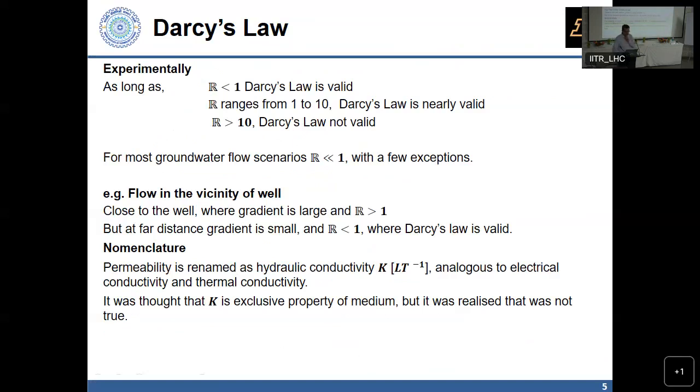We often see the term permeability. Permeability is sometimes different from conductivity depending on which sub-area you are from. In soils, people think of permeability as perhaps what we would call intrinsic permeability. It also comes from similar constitutive relationships like Darcy's law, where the flux is proportional to a gradient. We have in electrical circuits Ohm's law and conductivity, or Fourier's law when we do heat conduction.